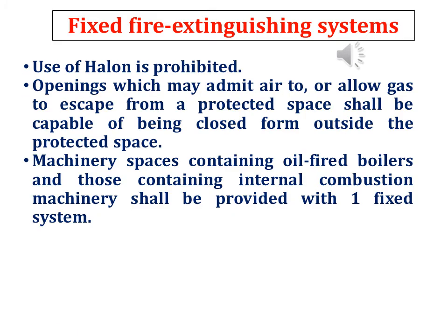Use of halon is prohibited. Openings which may admit air to, or allow gas to escape from a protected space shall be capable of being closed from outside the protected space. Machinery spaces containing oil-fired boilers and those containing internal combustion machinery shall be provided with one fixed system.